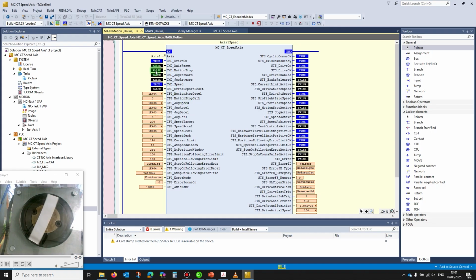Next thing that you've got, which I'll just show now, is motion stop. So the idea is that this could be used as part of a controlled stopping regime that could be part of an emergency stop, but can't be used as an emergency stop on its own. So let's just try that. And it's overriding. So there you go. That's caused it to stop.